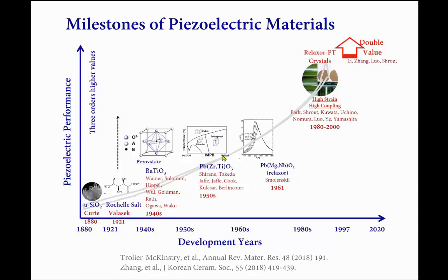And later on, another milestone is a ferroelectric solid solution system, where the perovskite members lead zirconate and lead titanate have high miscibility and form a morphotropic phase boundary, separating rhombohedral and tetragonal phases. Near the morphotropic phase boundary, they show very high dielectric and piezoelectric properties. This solid solution was reported in the 1950s by scientists in Japan and the United States, especially Bernard Jaffe, Hans Jaffe, and William Cook. They did a very good, extensive, detailed job on the PZTs.